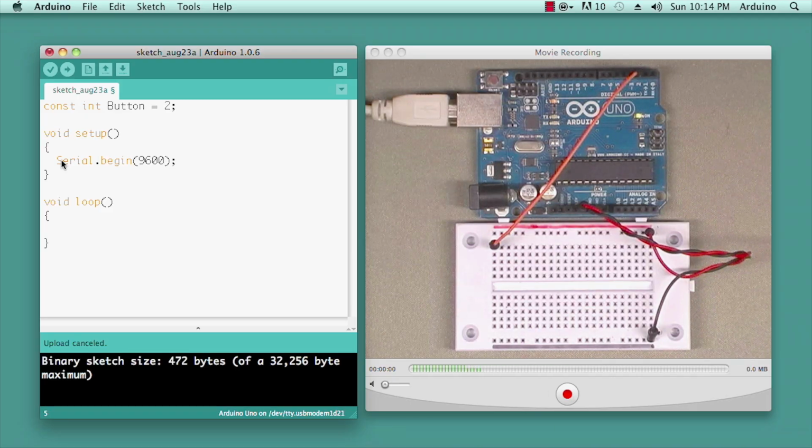And it's going to match the baud rate of the serial port. When we see the serial port open up later on, we can select baud rates in there. Bauds are just characters per second. So we're telling the Arduino that it's going to send information at 9,600 characters per second, and that's going to have to match the software serial monitor in the Arduino authoring environment, which will also be set to 9600. So that line just turns on serial communication.